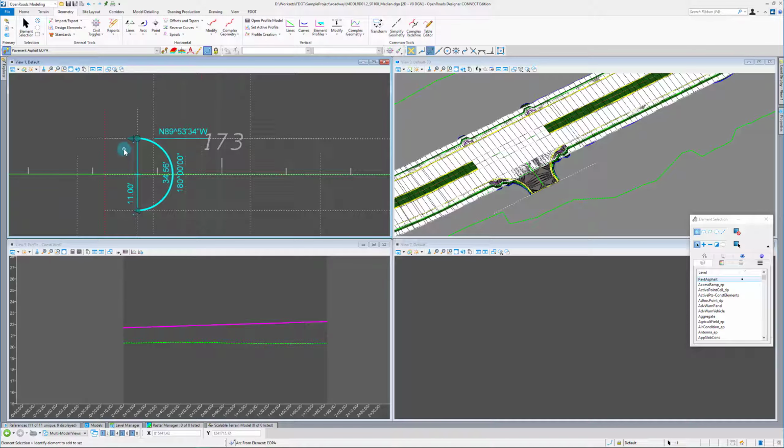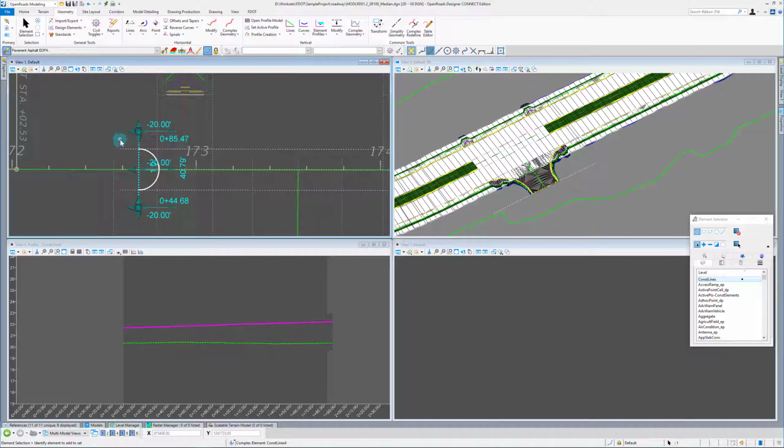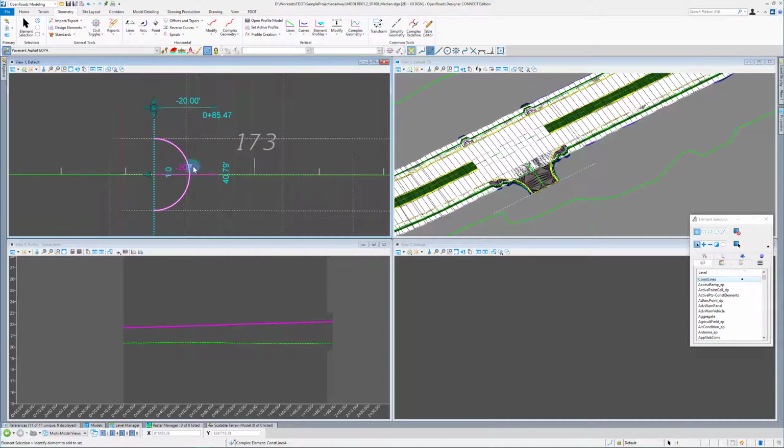So now I have this arc that if I want to change this to 20, it moves. And because I set up this boundary element to be 10 from that, all my boundary elements move too, which is very important. If I hadn't set up this boundary element and I only drew these 10 past this line, and I increase this to more than that distance, I might lose my profile, or I might lose that line. This could get pushed out further than that line was drawn. But since I have this boundary element and this is ruled to it, that will never happen.